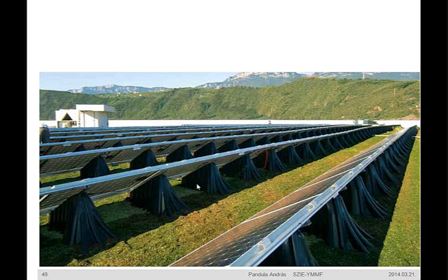The vegetation also grows beneath the modules, and in this case it's enabling the largest possible roof surface area to be greened. In addition to this, since the vegetation provides a cooling effect through evaporation, this increases the output of the solar power system by 5%, in contrast to other hot, heat-retaining roof surfaces. You can read more about the advantages of these modules on the OptiGreen homepage.